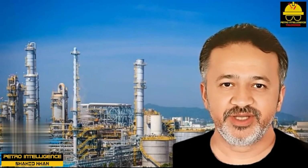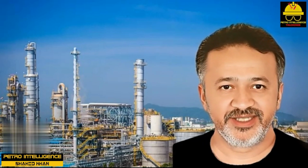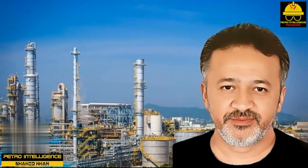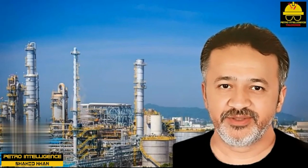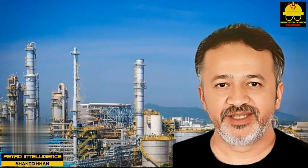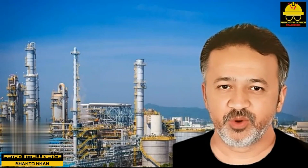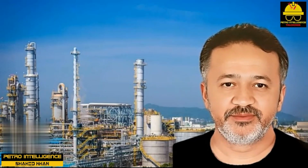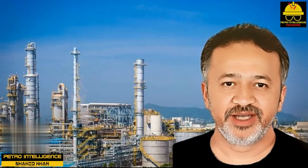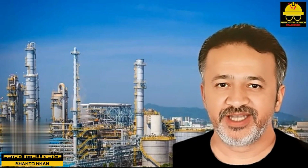Distillation tower turndown. The problem we have been discussing, loss of tray efficiency due to low vapor velocity, is commonly called turndown. It is the opposite of flooding, which is indicated by loss of tray efficiency at high vapor velocity. To discriminate between flooding and weeping trays, we measure the tower pressure drop. If the pressure drop per tray, expressed in inches of liquid, is more than 3 times the weir height, then the poor fractionation is due to flooding.